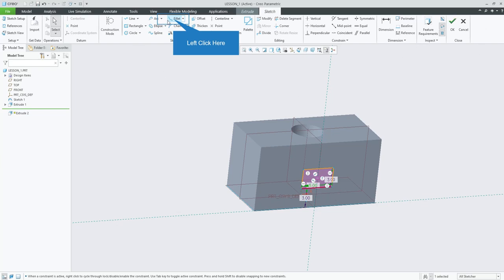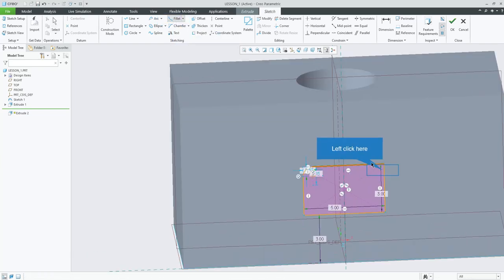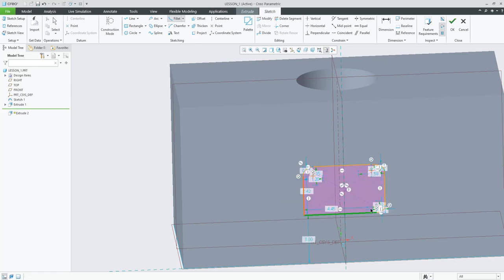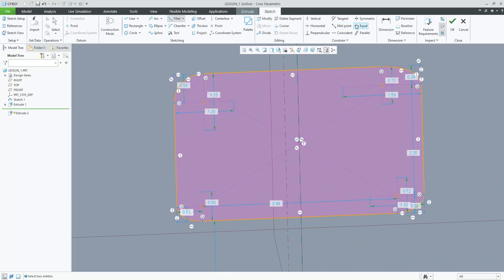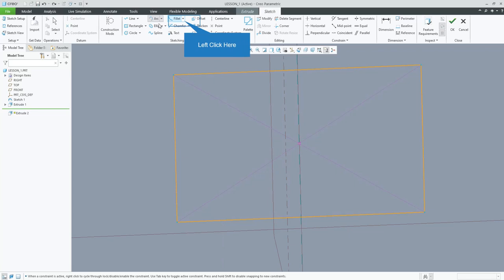And we'll throw a fillet on there for fun. Fillet, line, line, line, line, line, line, line, line. And we want those to all be equal to each other, so we'll grab the equal to constraint. Oh, wait a minute. We're going to undo that. One thing to look out for is it defaults to the last one you used.